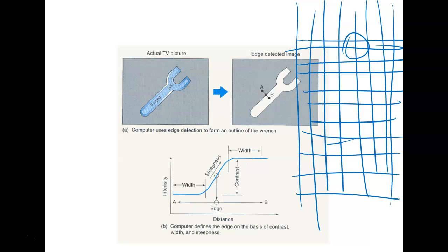Touchscreens? Yeah, HMI. I've seen those where it brings up a pattern. It has a plus, and you touch it and touch it and touch it. I know I have a calibration for this on this computer. I can bring up a calibration and it does exactly the same thing. It's got each corner, and I think one in the center, that you touch to calibrate it.